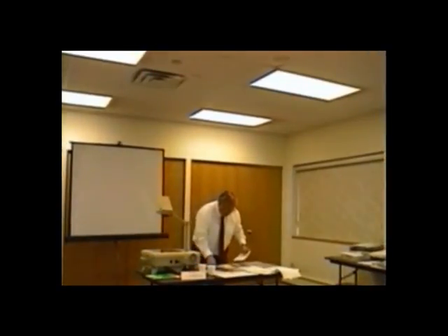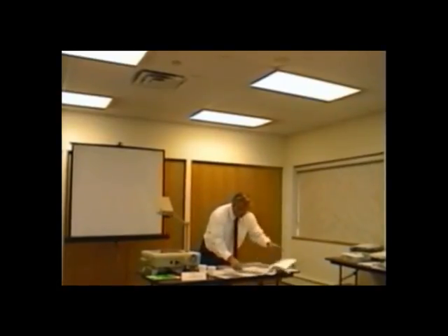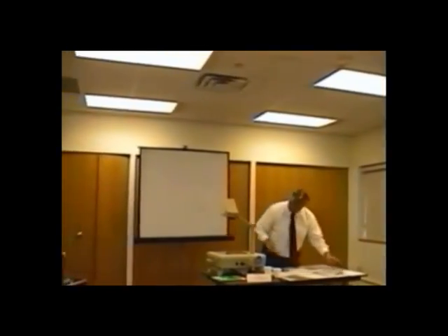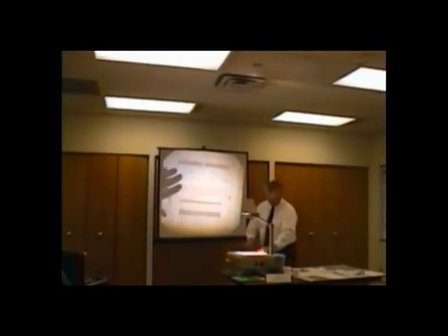And I want you to turn to your page 7. There's another chart. Okay, here we go. And it says, we're only going to use the first 2 columns up here. That makes it easy. Because on the left side, we have the sizes of the AC from 1.5 tons to 5 tons. And take a look at the line size for liquid line. This is liquid line size chart.